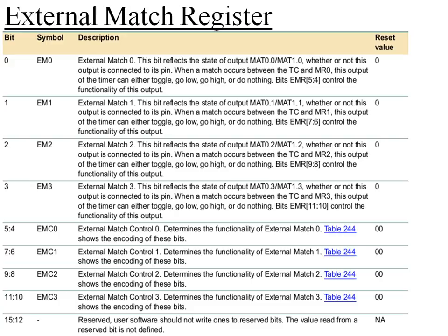Okay, and you have 8 more bits here, like EMC0, EMC1, EMC2, EMC3, where each channel again uses 2 bits. Now we have to program these bits. For example, EMC0 is nothing but channel 0. If I'm using channel 0, then I have to select a particular action by using these 2 bits. If you have 2 bits, it means you can go with 4 combinations. Now what are those 4 combinations?